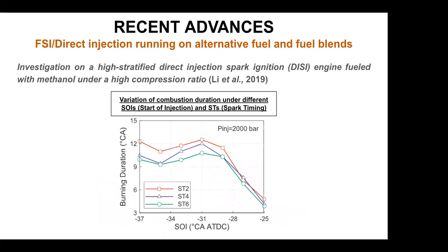Lastly, we can see the variation of the combustion durations of these different cases of start of injection. We can see that the combustion durations become shorter, especially for the cases with earlier start of injection. And that is all for the result of this study.